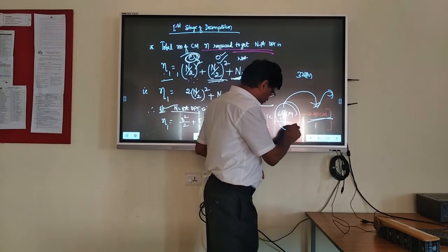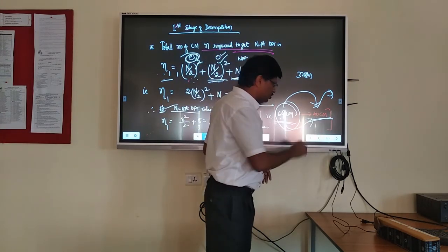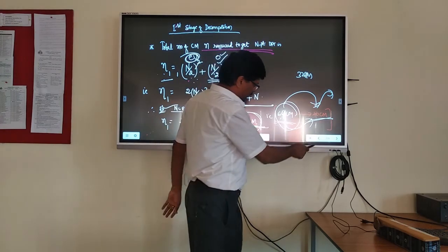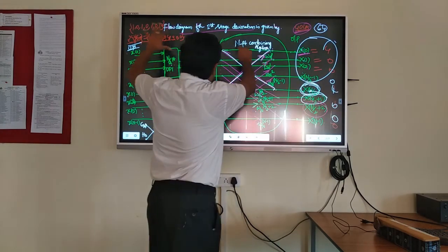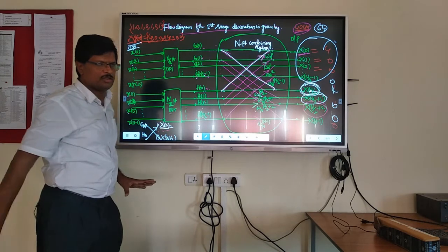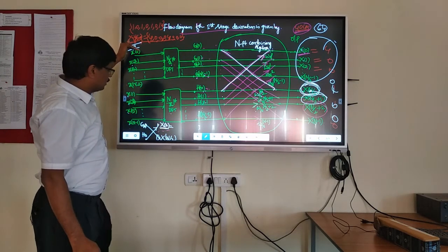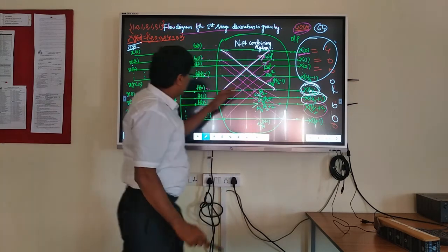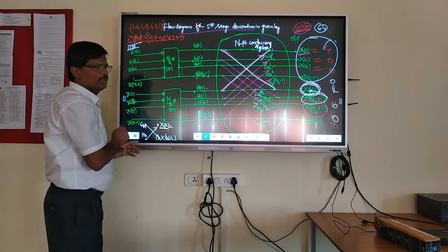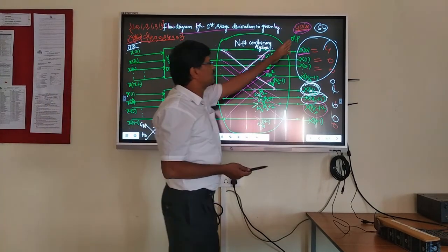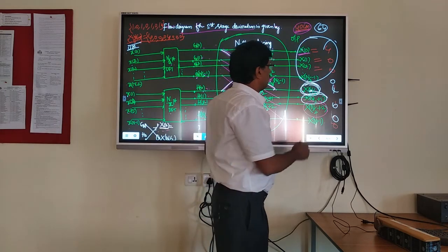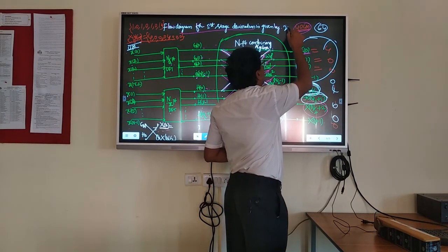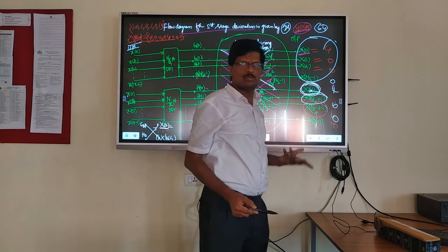Earlier 64 complex multiplications is being reduced now to 40 complex multiplications if you use this FFT first decimation algorithm to get 8 frequency sample output, same output from the same input. Now that means you are saving 24 complex multiplications.